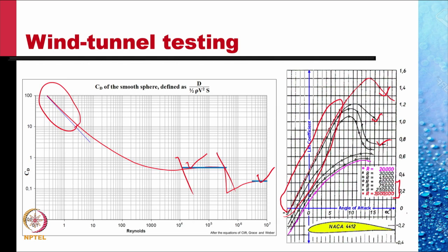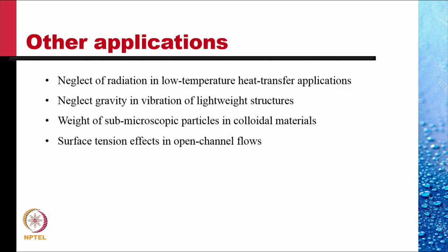And then the drag coefficient, lift coefficient, and moment coefficient that you obtain can be used to predict the forces and moment on the prototype. So all wind tunnel testing, or rather major wind tunnel testing, is quite independent of Reynolds number. Other applications of this neglect or weak laws are the neglect of radiation in low temperature heat transfer applications.